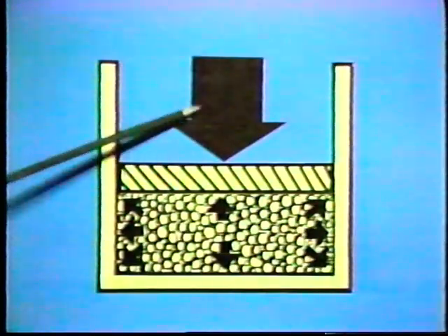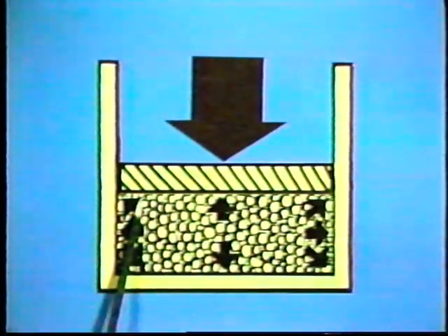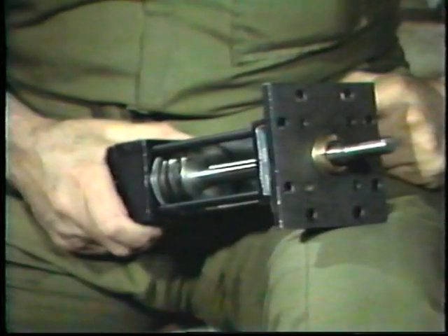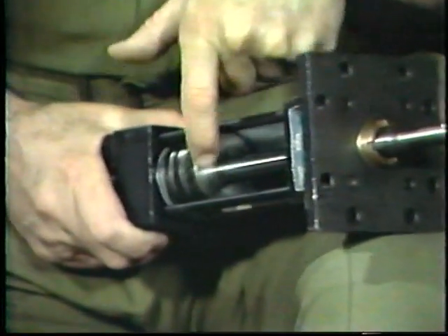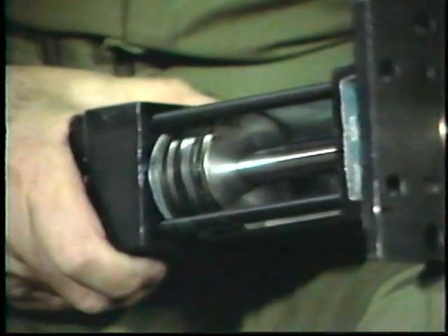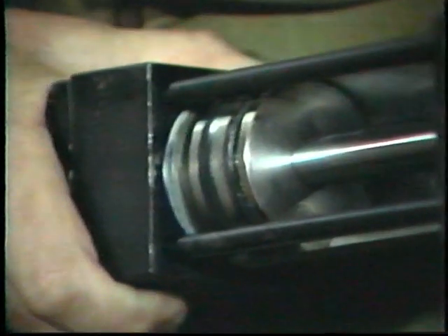Okay, the gas is under pressure and contains potential energy that can be used to perform work. But how do we know how much pressure is available? It depends on two things: the amount of force being applied and the surface area of the movable member being used to compress the gas. And since a piston, like this one, is the most common movable member used, we'll need to know how to calculate the area of a circle.